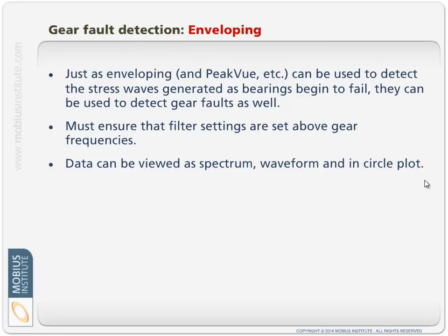We can talk about this in terms of stress waves and shock pulses and so on. The bottom line is we can detect that in the high frequency part of our spectrum, if we use these same techniques that we use for bearing analysis. And you may have seen it already.